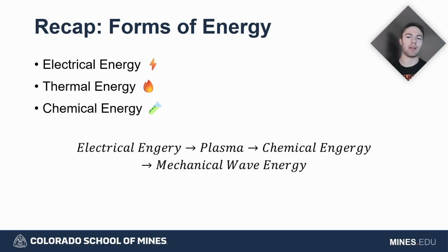And so inside that torch head, you have a very small voltage generator. When you press the button, it makes that clicking sound, that spark. Same thing that exists on barbecues, stoves, all that kind of thing. And so when you create that large potential gap between the electrode from the voltage generator and the outer casing of the torch head, which is your ground, there will be a spark that jumps between the 2. And that spark is essentially plasma inside of there. So it's superheating the air in between those 2 points, which then allows thermal energy to be released from the chemical reaction. So the air and the fuel in the tube are sitting there.